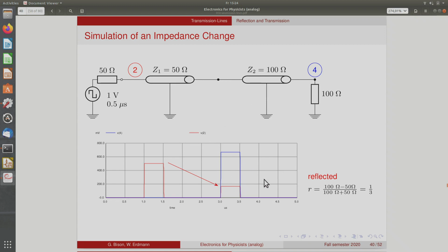So here you have a higher amplitude actually than the incoming signal, traveling along the second line. And if it's properly terminated here, there's not really a problem. So the signal arrives, but it arrives with a different amplitude. And if the reflection to this end is not a problem because there's no receiver there, then it's fine. But still, yes. So this is the transmitted factor 4/3. The transmitted is larger than the incoming.